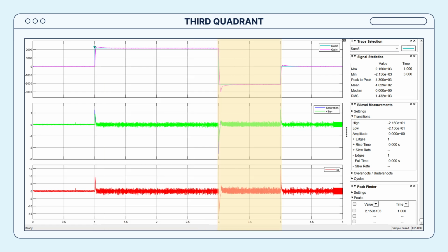Quadrant 3 involves the DC motor operating in reverse motoring. The graph shows the segment where both the current and voltage are negative during this condition. The torque and the speed are negative as well, hence causing the direction of torque to be clockwise and the power is positive. During reverse motoring, the motor converts the electrical energy to mechanical energy, driving the load backward effectively.